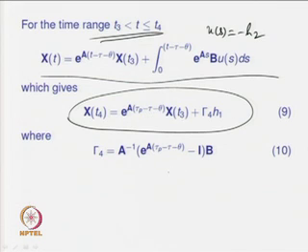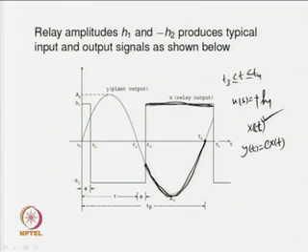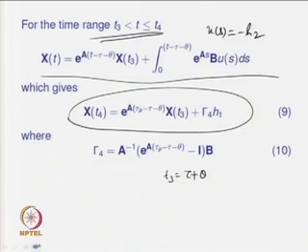What is t3? x(t3) is nothing but where we are starting. So this will be tau plus theta at t3. If you look carefully, from t0 to t2 it is tau seconds, and from t2 to t3 it is theta seconds. So from t0 to t3 it is nothing but tau plus theta, that is why that is acting as the initial value, and you are getting the term tau minus theta in the expression.